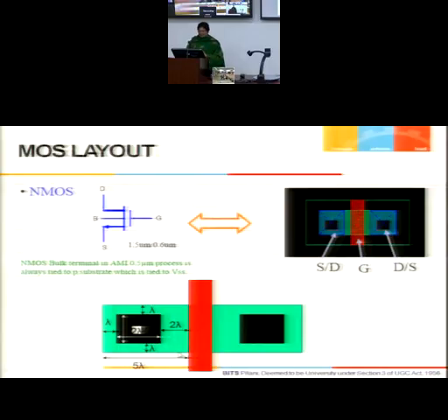So we have a gate structure. Beneath this will be oxide, beneath it will be silicon. So there would be a MOS structure. This is going to be your source junction. This is going to be the drain junction. And then we have design rules which say that if there is a contact, it should be 2 lambda by 2 lambda. We are following the lambda based design rules, and there should be an extension of lambda from all sides. And you should have a minimum distance of 2 lambda between contact and the polysilicon. These are a few design rules that we take care of while we do the design. That means the minimum junction length has to be 5 lambda.